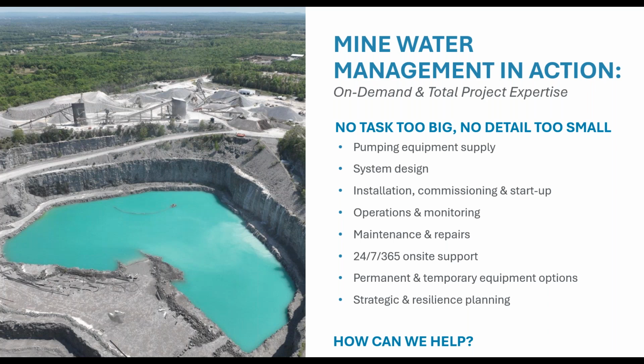But it's an all-in-one unit with the motor, the pump, everything is compact and is not going to leak. Whereas a vertical turbine pump or a surface mounted pump gives you the opportunity to work on different parts of the pump and maintain the motor separately from the pump end if necessary.